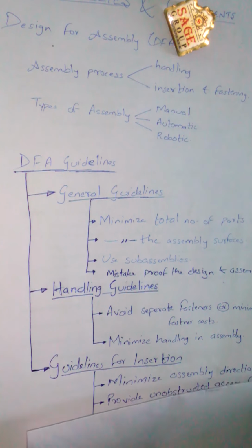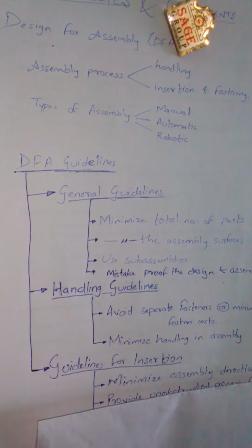Now what is meant by this? All products should be designed so that they can be assembled from one direction. Alright, rotation of an assembly requires extra time and motion and it may require additional transfer stations and fixtures. The best situation in assembly is when the parts are added in a top-down manner to create a Z-axis stack.